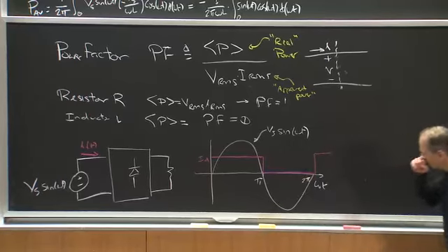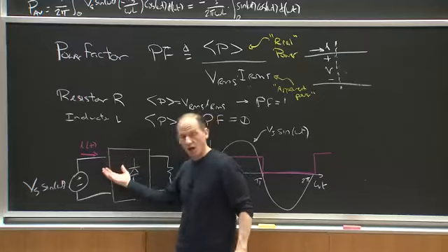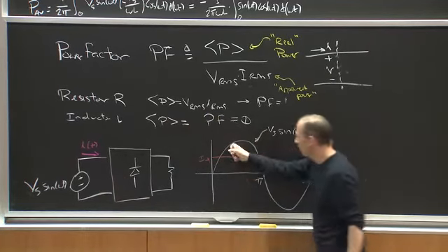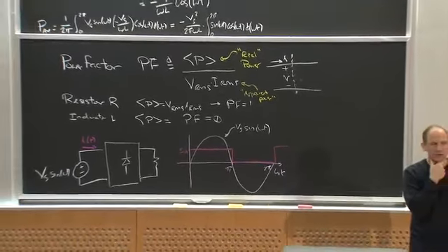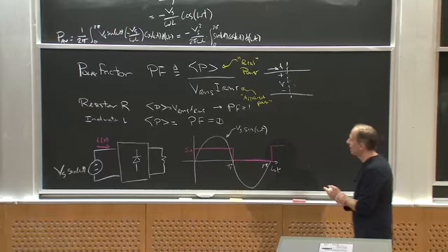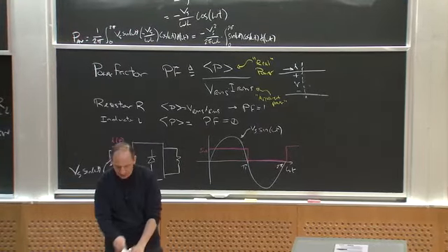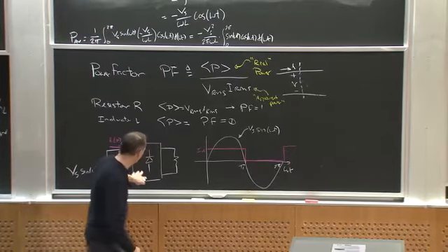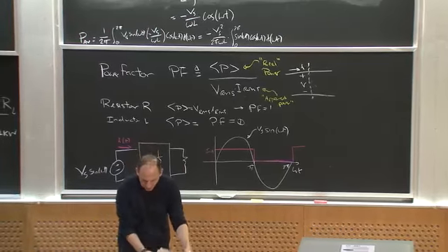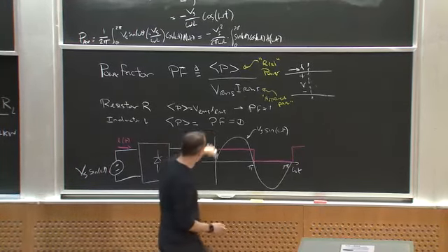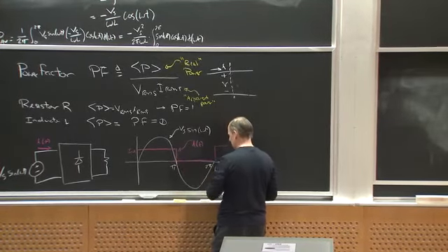The point is, when we start introducing power conversion, we can often have nonlinear loads, meaning that even when I'm driving it with a sinusoidal voltage, I don't get a sinusoidal current. So let's think about how I might represent that case. This was a half-wave rectifier with an inductive filter, which draws that kind of square wavy waveform. Let's think about how I might represent this current I of t.